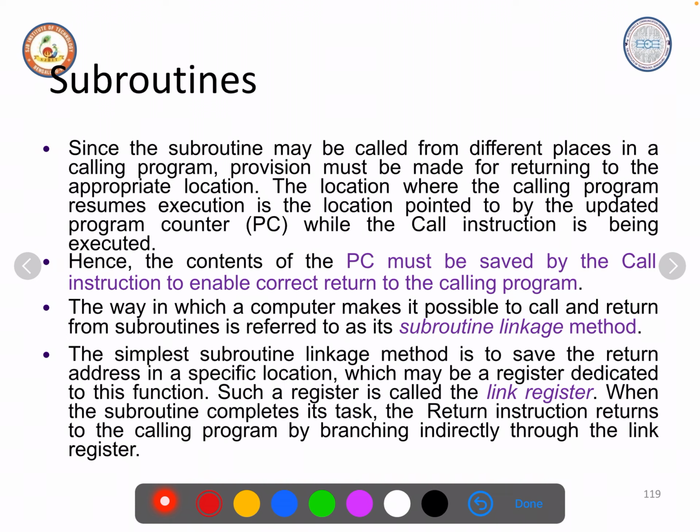So it is actually a linkage method. You will make use of a link register here. The program counter content will be copied to a link register, a special register which is used to store the subroutine return address of the main program.